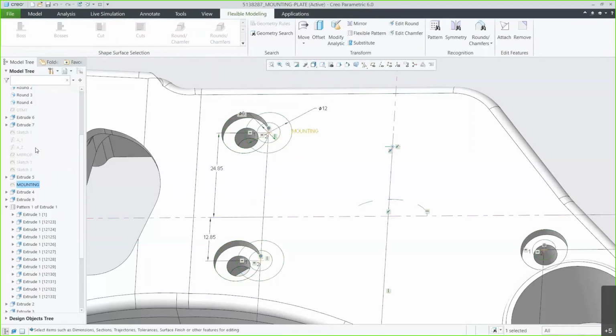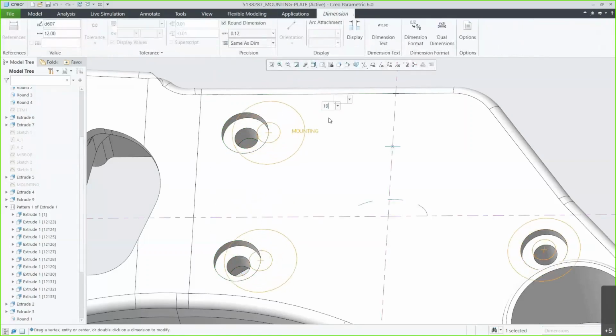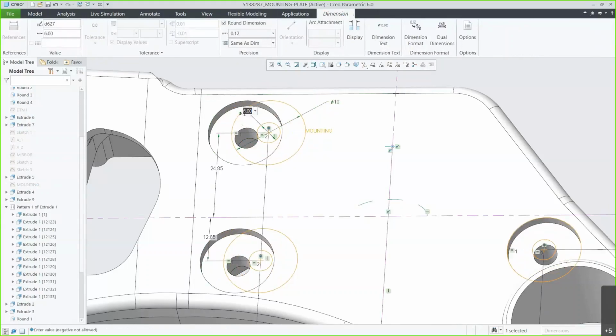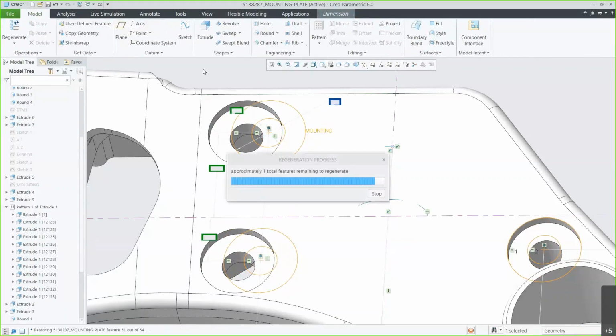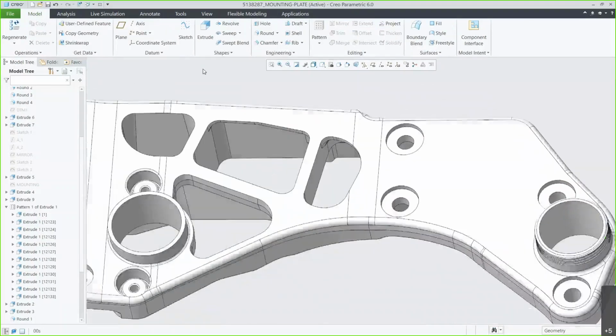So now I've moved those around, but what happened to the original sketch? Well, those are still right there. I haven't deleted any of that underlying intent that went with those. What that allows me then to do is go back and change the cut hole diameters if I'd like to. Maybe if I make them a little bit bigger, you can see that we still have that move command happen after those changes, but it still maintains that design geometry.